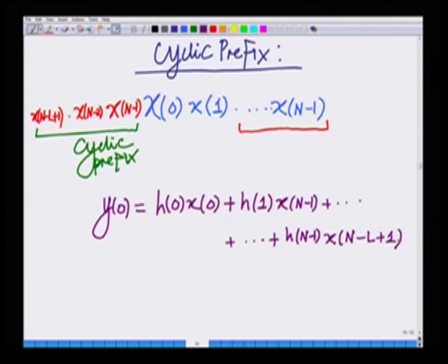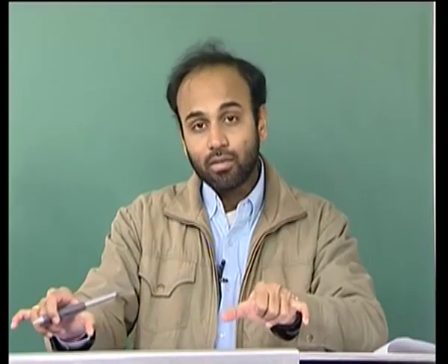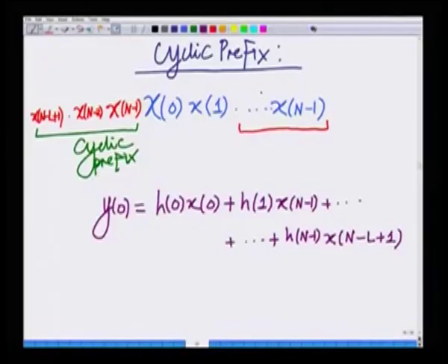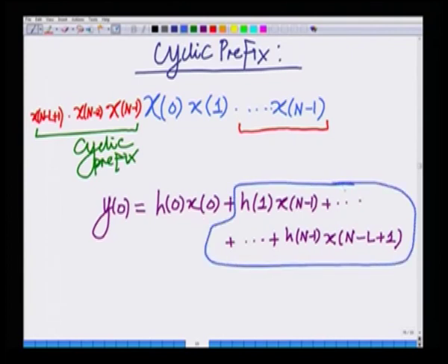So, now because we are not directly transmitting the two OFDM symbols next to each other, instead we are cyclically taking some of the last samples of this OFDM symbol and prefixing these samples to the current OFDM symbol, I have removed the impact of intersymbol interference on this OFDM symbol. Alright, so now you can look at this part, all the samples of y0 belong to the current OFDM symbol.